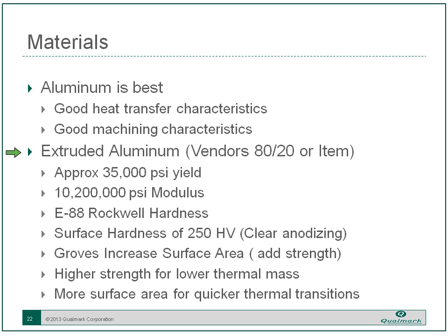In HALT, we use a lot of the extruded aluminum shapes, the 80-20. Those are also valuable for HASS fixturing. It's very strong, and once you put something together, it stays put together even in a HASS situation. And it's relatively straightforward to go through and check and make sure that all the connections are still tight as part of a PM, and can speed up your fixture implementation. You can build just about anything out of that stuff.